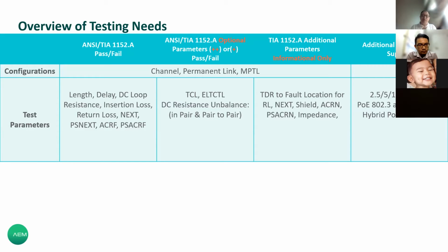We are concerned about noise because now cable, especially Cat6a, we are talking about 500 megahertz in terms of the frequency performance. Okay, the bandwidth is wider compared to Cat5e, which is only 100, while Cat6a is 500, and for Cat8 we are talking about 2 gigahertz frequency.